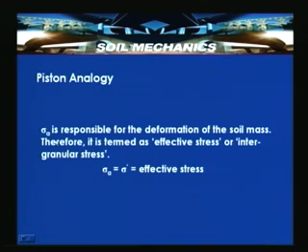In the piston analogy, sigma dash is responsible for the deformation of the soil mass, so it is also termed the effective stress. In the case of a dry soil, when there is no water within the voids, that is uw is equal to 0, whatever total stress is applied is the effective stress, which is responsible for the deformation of the soil mass. So, sigma is equal to sigma dash, the effective stress, in the case of a dry soil mass.